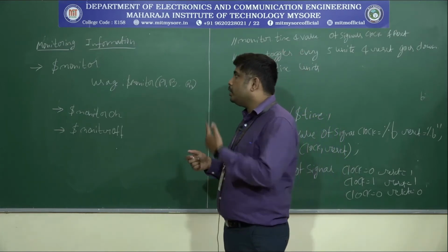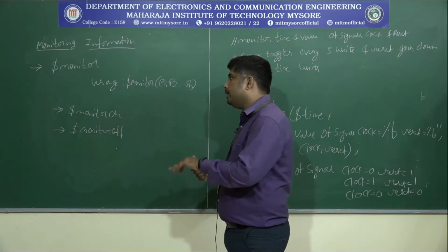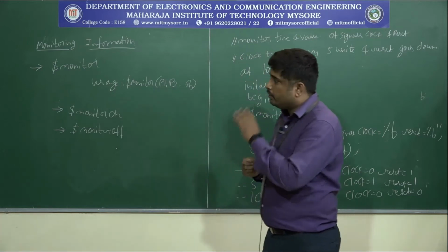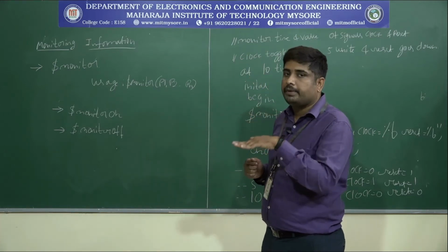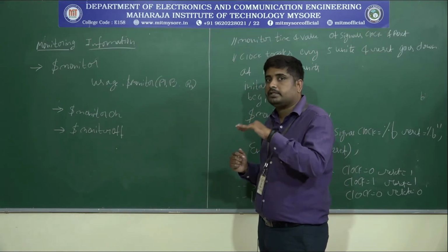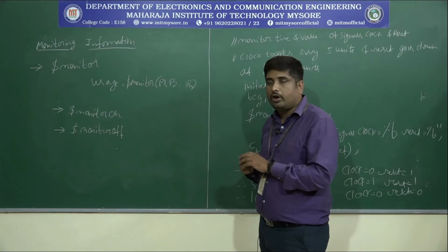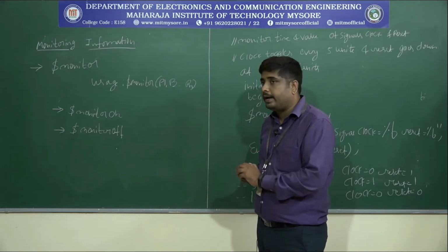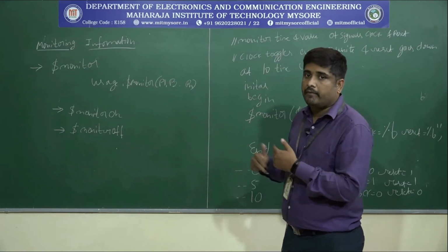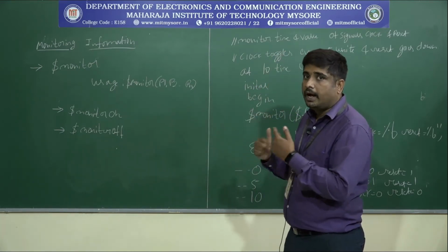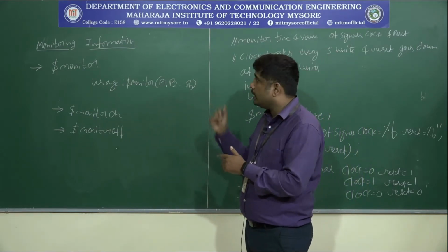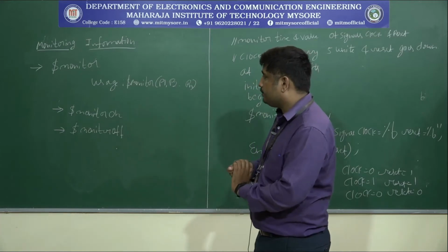So why is $monitor more special compared to $display? Because here you have to monitor the current information, especially the current simulation time, because it's very important. Using $monitor, we monitor the current simulation time. Again I repeat: when the current simulation time changes, at that time it monitors as well as displays the information. That is the specialty of $monitor.